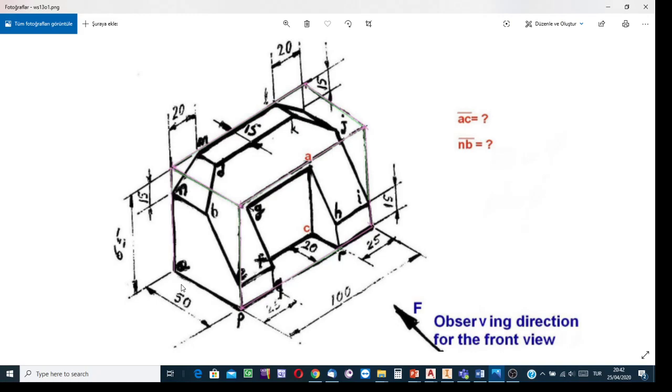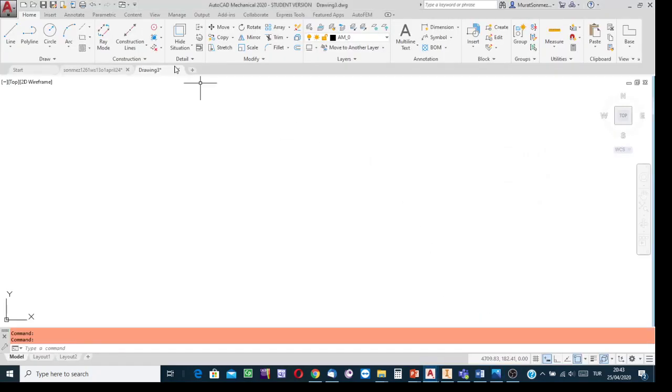I'm going to draw a rectangle as the first sketch and consider that rectangle as the bottom side surface. And in applying the extrusion process, I'm going to create the rectangular prism. The extrusion length, the height of the prism, will be 65. Okay, then do it. Still, I can use 2D or just change the mode from 2D to 3D.